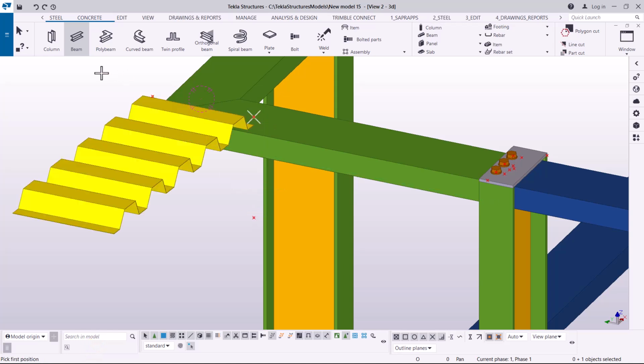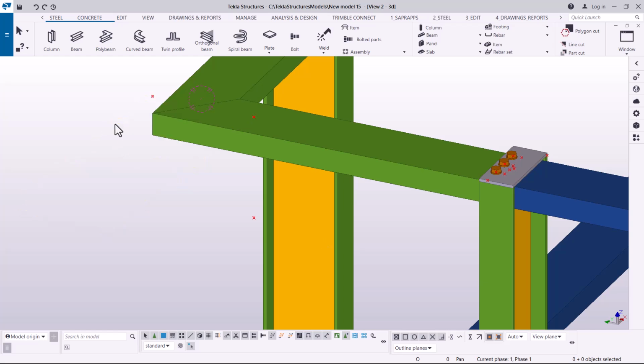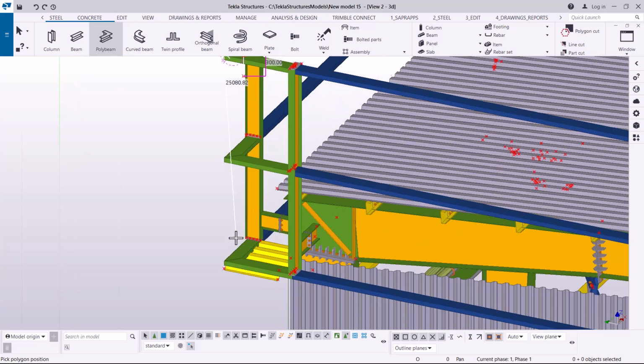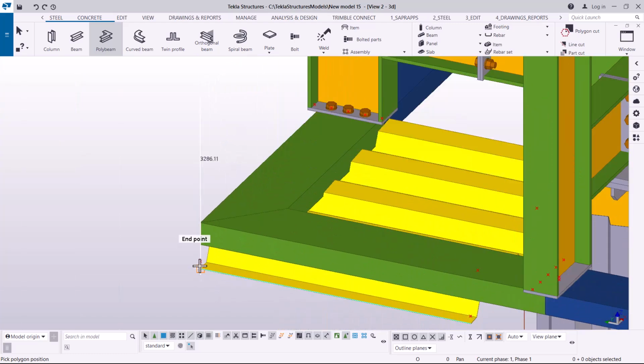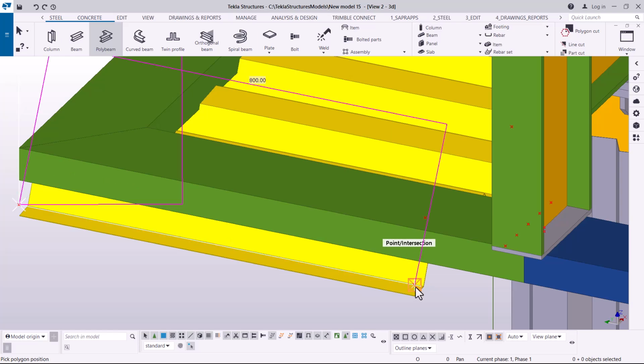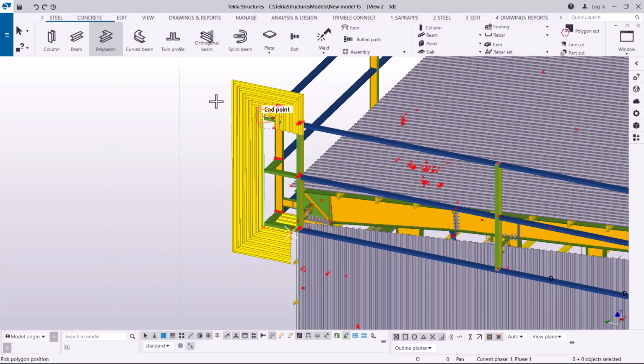And what I've just done is I didn't pick on the polybeam. So let me just go back and pick polybeam. Then let me this time start from that spot, move to that spot, and move to the bottom end here, and pick on that, and pick on this. Then press my middle button on the mouse.